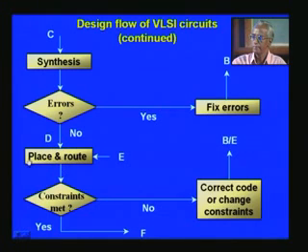And once you are here, what it does is it places different primitives, gates, muxes, etc., what we have already seen, at strategic points. It locates the optimum possible point, and you can also specify your IO pins, etc. And finally it starts routing. Routing is, having placed different components inside, it starts interconnection. That's what you call routing here, and this is a time-consuming process.